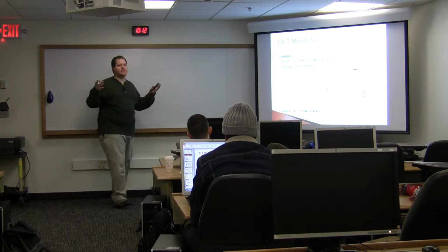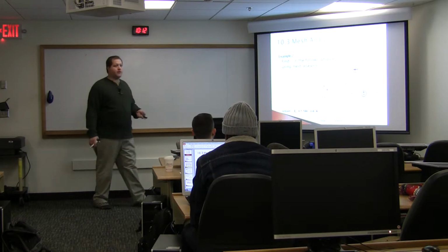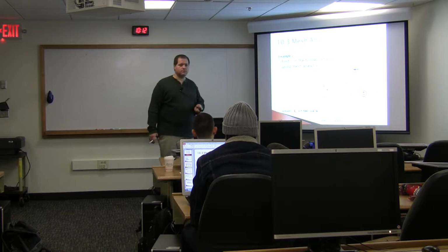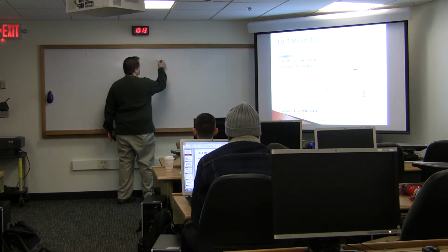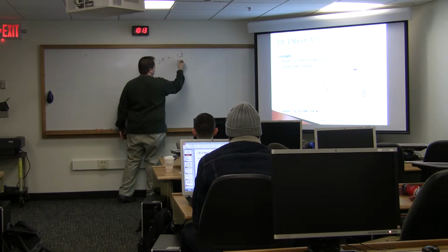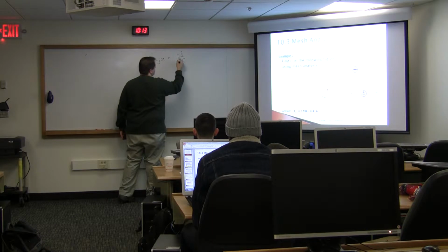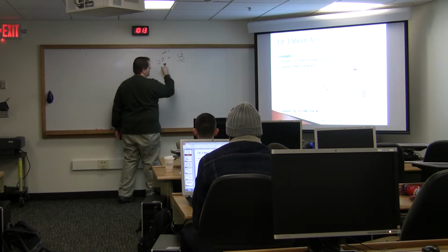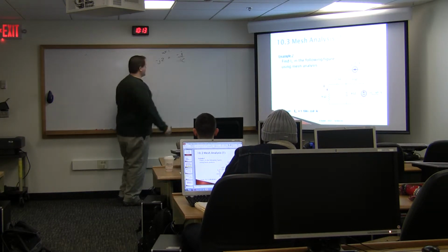So I don't want you to feel like, I can't simulate this, or I can't build this in the lab because I don't know what frequency, so I don't know what real value of capacitor or inductor I have. It's okay. Now, if you build this for 60 hertz, you're going to choose a capacitor and choose an inductor that yield that value of capacitance, right? You're going to plug in and say, the capacitor is negative j2, and that relates to negative j over omega C. If I let omega equal 1 even, right? If I plug that in, omega is 1, and I can solve for C, right? C is going to be a half.